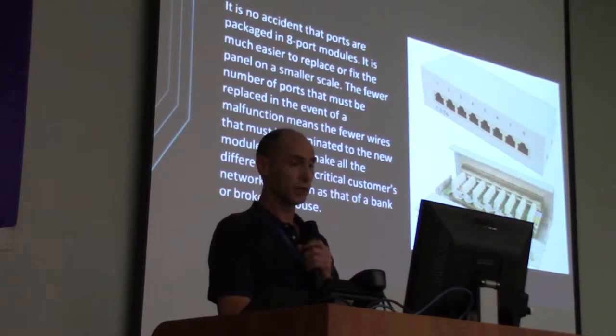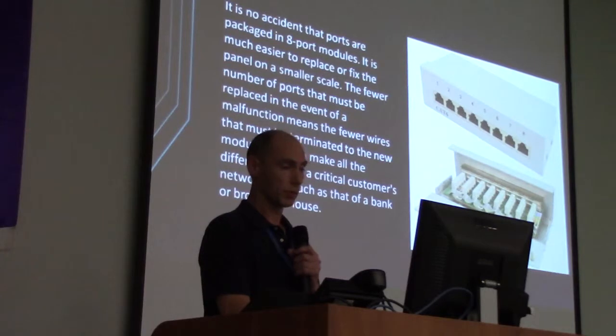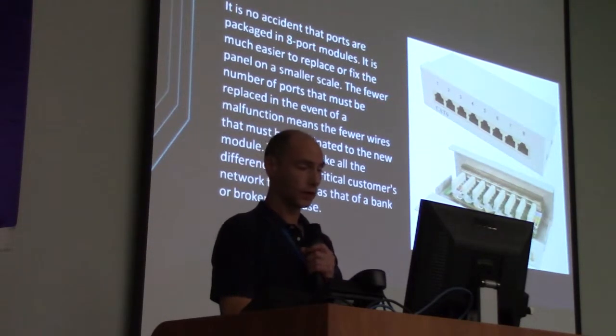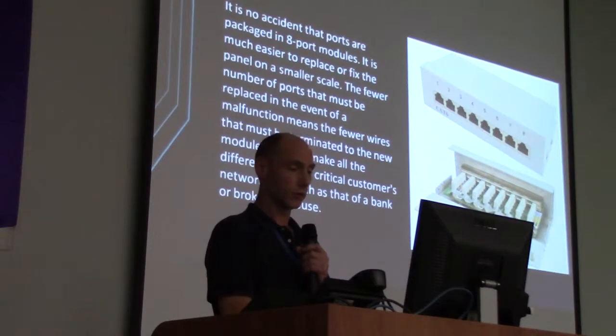But it is no accident that ports are packaged in an 8-port module. It is much easier to replace or fix the panel on a smaller scale. Fewer number of ports that must be replaced in the event of a malfunction means that the fewer wires that must be terminated to the new module. This can make all the difference when a critical customer's network fails, such as that of a bank or a brokerage house.